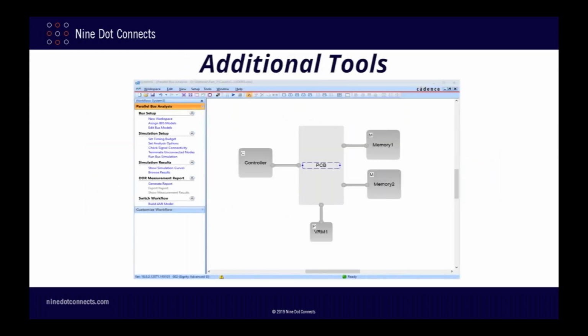While we're on the subject of changing simulation parameters to play what-if games, I'd like to tell you about a few other things that we can do to give us more information about the design. SystemSI gives us the option of connecting the PCB signals directly together instead of having physical traces. Known as auto short, this function essentially removes the signal integrity effects of the PCB from the equation and lets us focus on the active components themselves.